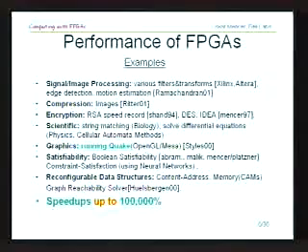So here are some of the examples that I had in mind when I said before that we have up to 100 times the performance. People started in the beginning doing the obvious thing, taking signal processing algorithms, putting them on an FPGA, and showing that for many signal processing algorithms you can actually perform quite well compared to microprocessors. The reason why they're not currently switching everything from microprocessors to FPGAs is simply there is a cost problem, and you can't really get the same cost benefits that you have for a microprocessor.